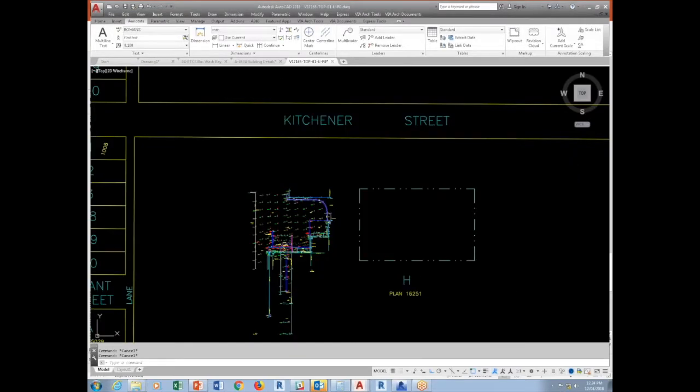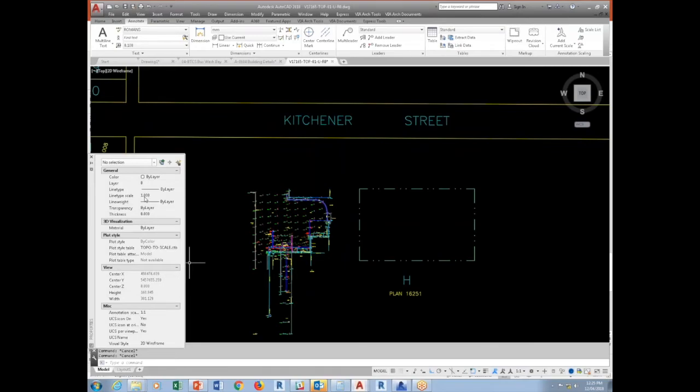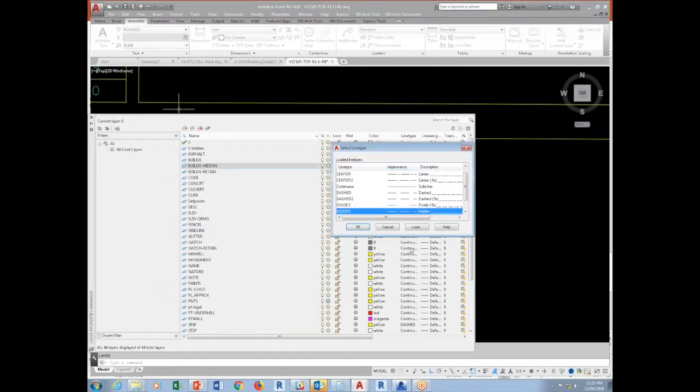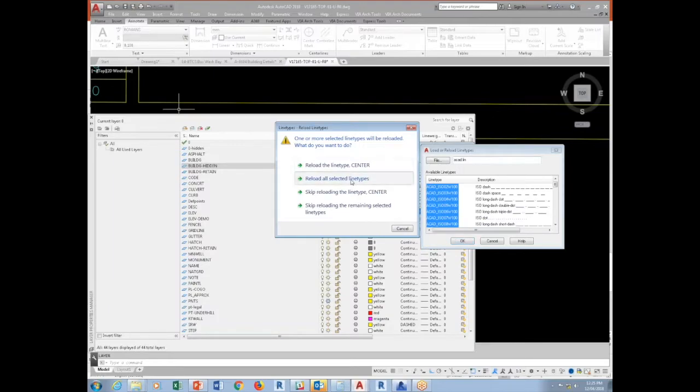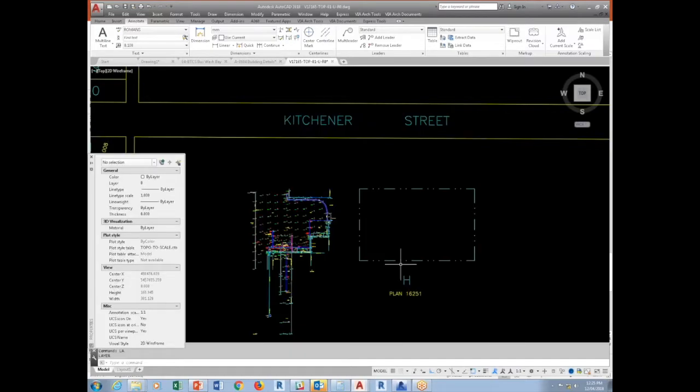And then what people tend to do with that is they go in here and change all this line type scale to make it look correct, right? Don't do that, okay? If you do run into this problem, the simplest fix is, let's say you want to convert this line type into Imperial, first thing you do is type in measurement, okay, like what I said. Then you go to layer, and then you reload all the layers and say okay. And then you say you want to reload them all? Yes. Okay, fine.